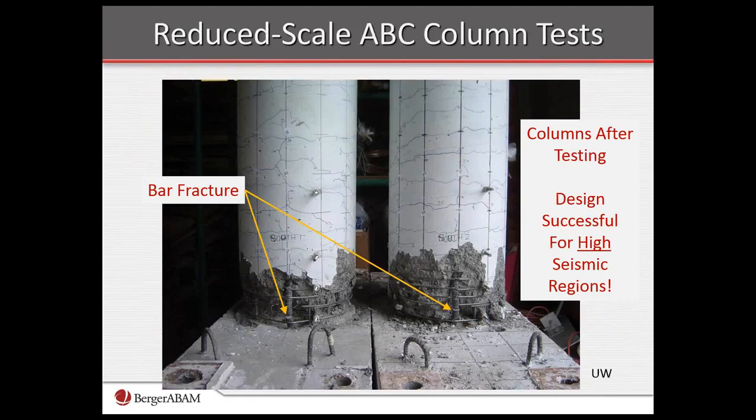If we look at, let's say, another set of columns, in this case, these were precast columns that were connected with grouted-duct couplers to a foundation element. And in this case, you see that after testing at that larger drift ratio cyclic testing loading regime, we eventually were able to break the longitudinal bars and achieve ultimately the strength and ductility of the section. Eventually we lost that as you break those bars and start to break the spiral as well.